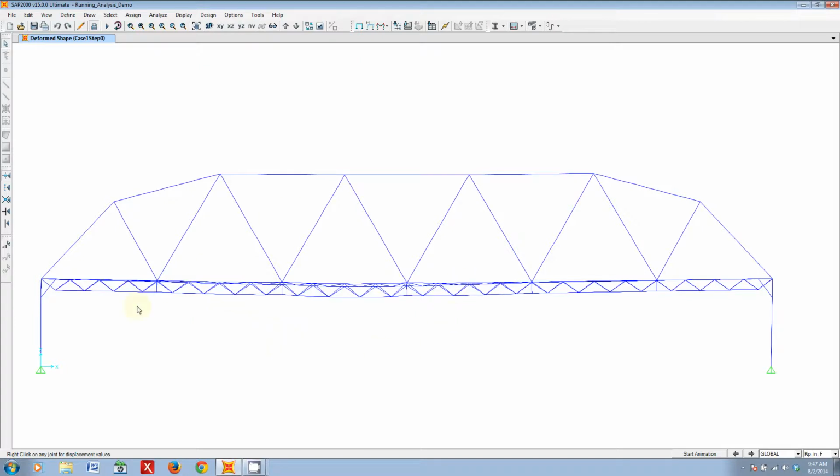Now that's great. We can view deflections, and check it out. If I go to a particular point, it'll automatically pop up with the point object's name and the U1 through 3 and the R1 through 3. So the U1 through 3s are pretty much the deflections in each of those different coordinate directions. So basically 1, 2, and 3 directly correspond to X, Y, and Z. That means U1 is the deflection in the X direction, U2 is the deflection in the Y direction, and U3 is the deflection in the Z direction.